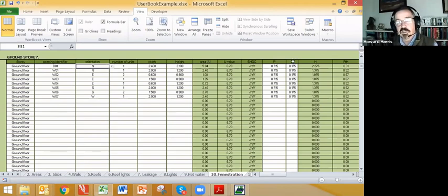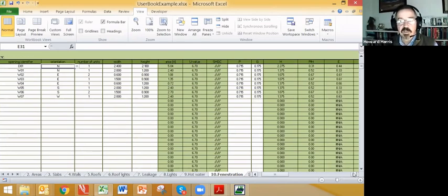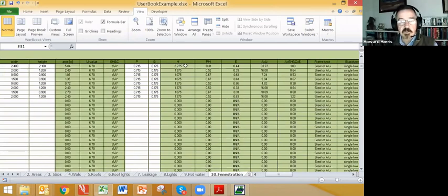You also have your G value, also explained in the training, which is the distance between underside of lintel and underside of shading device. So all of those need to be calculated, input, and then the system calculates for you the H, which is the sum of your height of window plus the G value. It calculates also your P over H ratio, a critical ratio, in looking up the appropriate solar